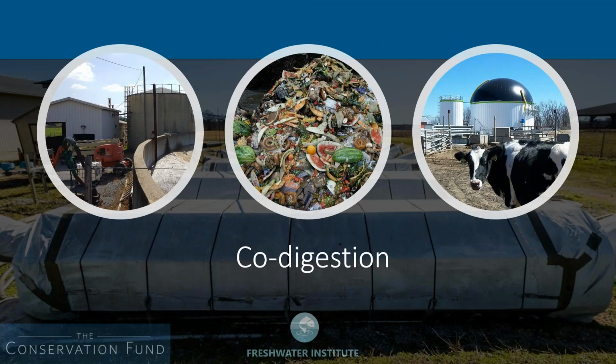Co-digestion of organic waste is basically the digestion of waste organic matter, such as agricultural waste or food waste, along with dairy manure or wastewater sludge. Basically, it means the mixture of two or more different kinds of waste, instead of just digesting one kind of waste. In the case of aquaculture systems, it could be the addition of fish offal into the aquaculture waste stream. The advantage of co-digestion is that it can help increase biogas production dramatically in some cases and result in a higher return on investment for aquaculture practitioners.